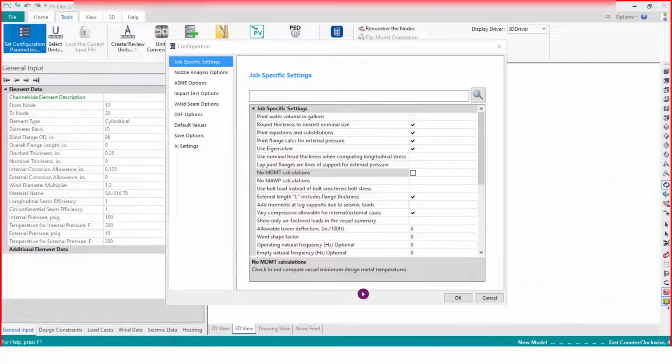So let's say the software has analyzed and told you that this particular geometry and material can sustain -20 degrees Celsius. And if because of the process or the environment your requirement is -10, it can sustain more than that, so it is safe. But if your requirement is -30 and the geometry you have selected can sustain only -20, in that case impact testing we need to perform.